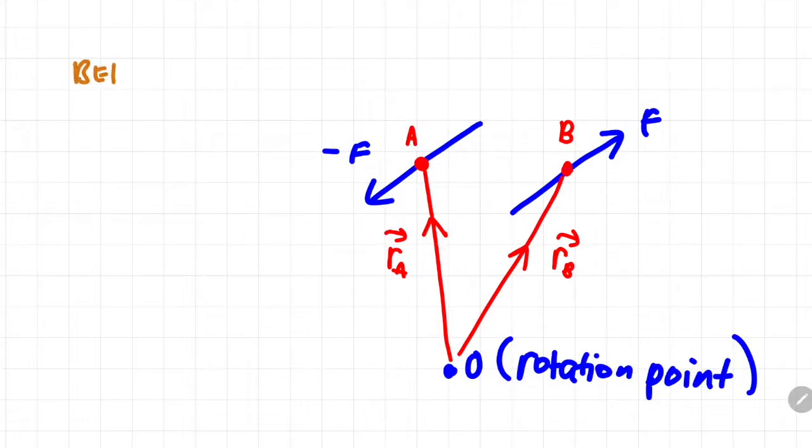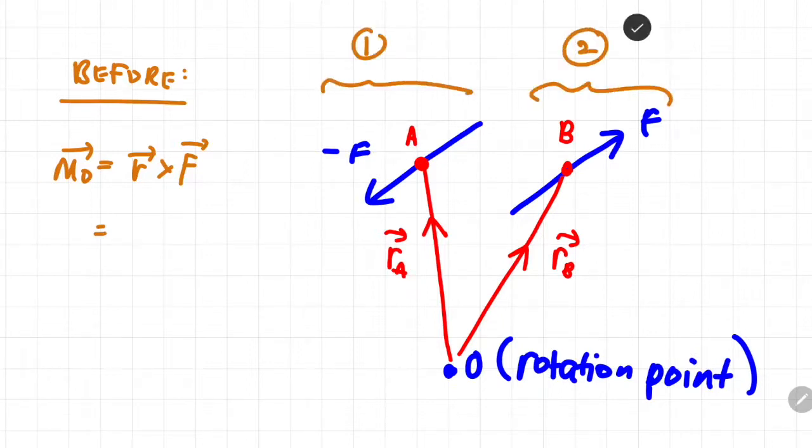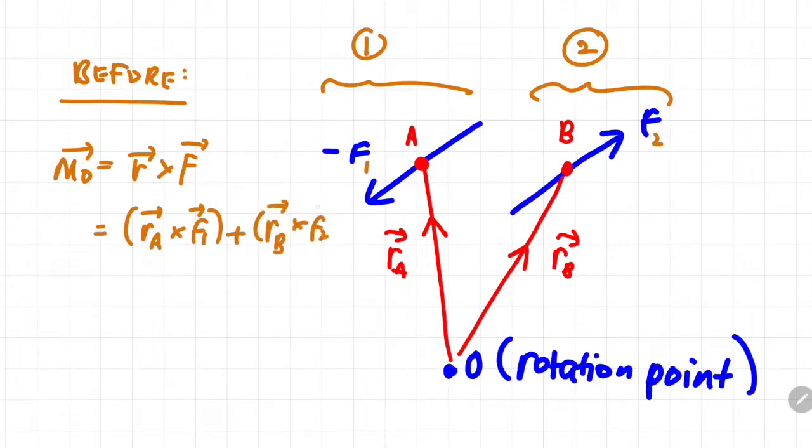Based on the previous vector formulation, you can get the Cartesian vector of the moment by using cross product, whereby position vector cross product with the force vector. So looking at this system, there are two forces. Okay, let's call this force 1 and let's call this force 2. So in order for you to get the resultant moment, you have to cross product RA with F1 plus the position vector B cross product with F2. So this becomes a little bit macam tricky lah, and the calculation process becomes a bit longer.